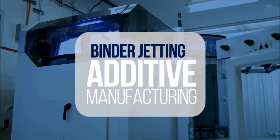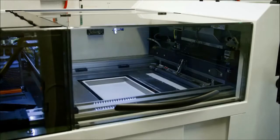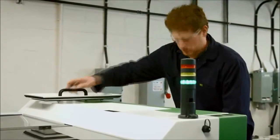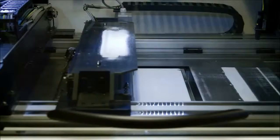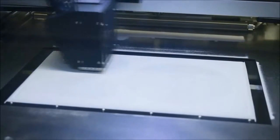Binder jetting, also known as powder bed printing. Binder jetting is similar to a regular inkjet 2D printer. A binding agent is deposited in a layer of powder from a print head. The liquid binding agent joins the particles together and binds the existing layer to another layer of powder.